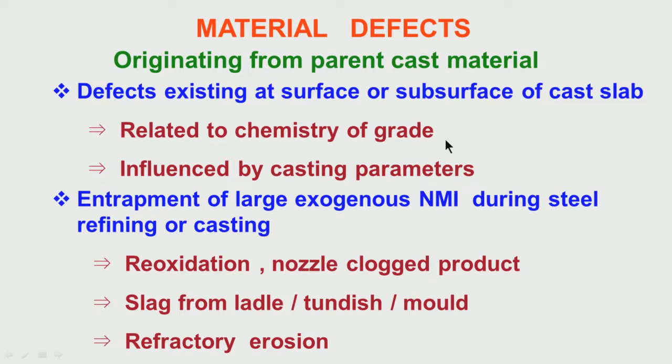As I have told you, laminations sometimes come from the surface, sometimes from depressions. Those laminations which are located near the edges are coming from certain specific depressions, which originate from particular grades like 0.1% carbon, the so-called peritectic grade, or 304 stainless steel, again the so-called peritectic grade in the stainless family.